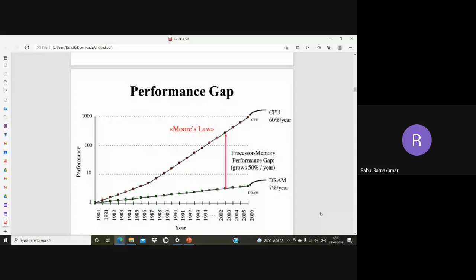That is primary memory. Other memory like SRAM consists of registers or high-speed memory within the processor, like caches and other things. That is very costly and takes a lot of area also, so we won't consider that as primary memory. So we put the DRAM. DRAM speed is much less compared to processor speed. So this is the bottleneck. Moore's law is allowing us to reduce the size of the transistor, but the disparity between memory and processor speed is still huge.